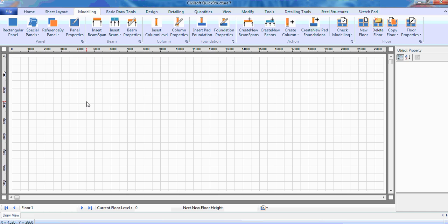Now, to build models with the software, let me quickly paint a scenario. Usually, assume, for instance, you have a building plan, an architectural drawing, and you want to design the architectural drawing structurally. The first thing you do is to plan your drawing. First of all, you map out your GA, the first floor GA, the second floor GA, the roof GA, and all the rest. Then of course you now need to know the positions of the columns and all the rest. And then again, to map out the floor GAs, basically you have the panels, the beams dividing the floors into panels.